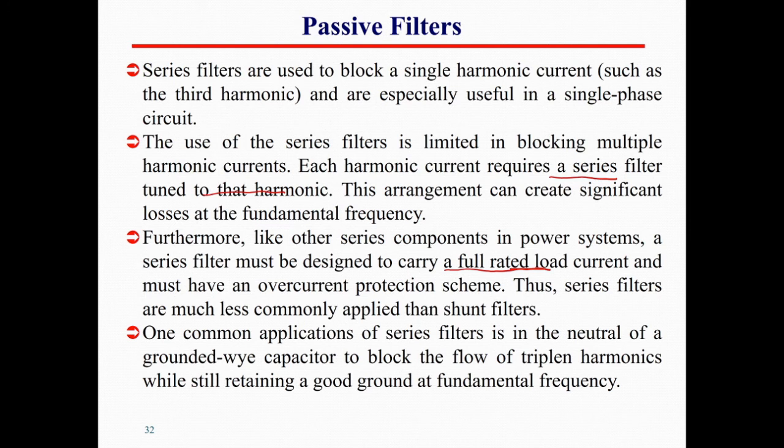One common application of a series filter is in the neutral of the grounded Y capacitor bank, to block the flow of triplen harmonics while still retaining a good ground at fundamental frequency. Okay, so this is what the series filter is doing.